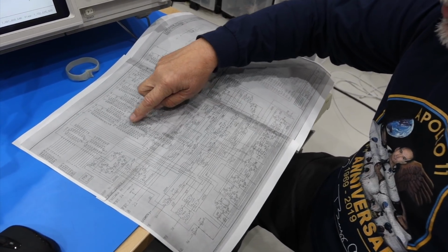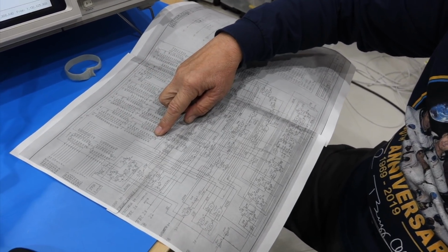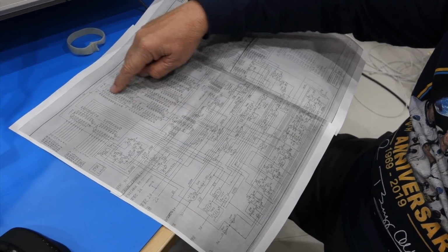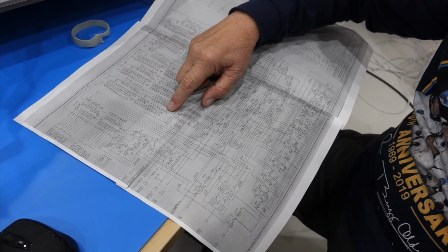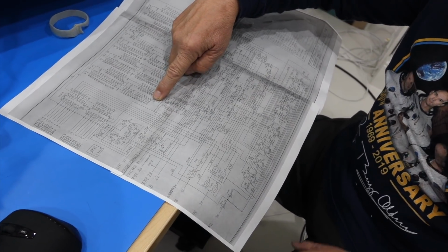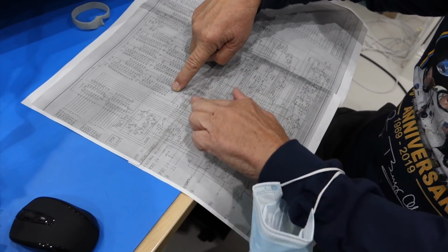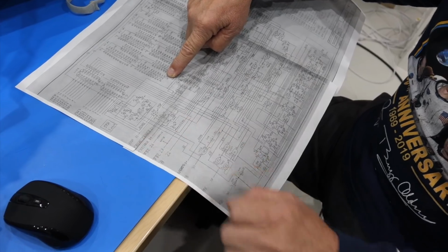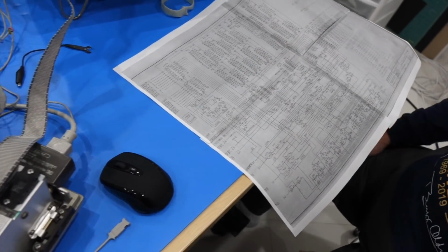So we're going to quickly check. The first thing it should be doing is reading from location 40, so bank 0 of the ROM here. This is the select line. We should see it go low to select the ROM. If that doesn't happen, the problem is this way in the logic for selecting ROM. Right, or on the buffer out, right?